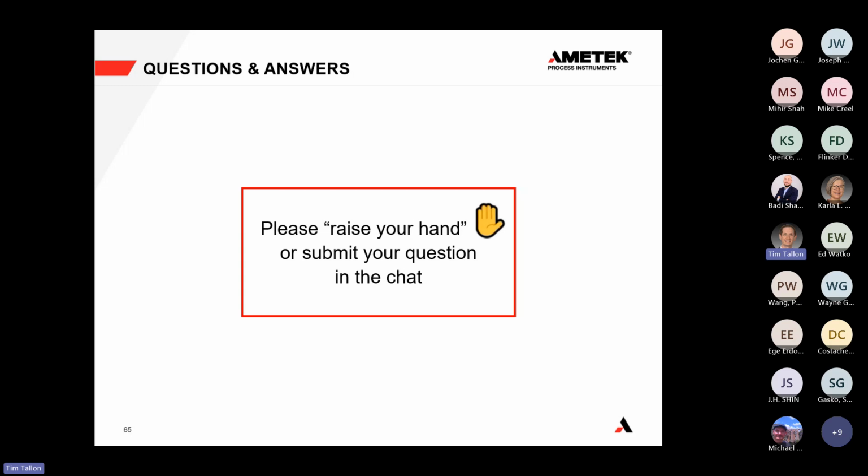You also want to make sure that you have sufficient time for the reaction to take place, but you don't want to be in the flame where the reaction is taking place, and there's going to be a lot of variability. So what API 556 recommends is that you put it right at the end of the radiant section, right before the convection section.